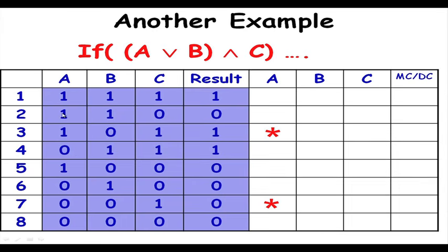What about 1 0? Now, 1 0 is here. So, here also the outcome does not toggle, but look at the third one: A is 1 and B, C are 0 1, and in the 7th one A is 0, B, C is held at 0 1 and the outcome toggles. Or in other words, 3 and 7 will achieve independent evaluation of the basic condition A.